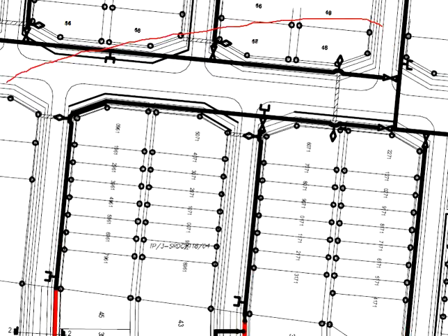Now, by looking at the layout of the water reticulation system here, can you tell there is a mistake in terms of the proposed layout? Something is wrong with the layout. These buildings cannot access the water main. Theoretically, there should be another water main here.